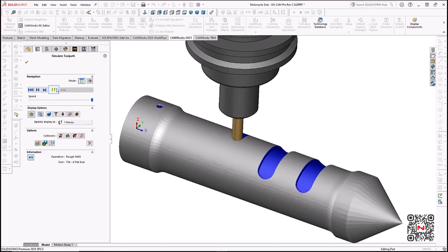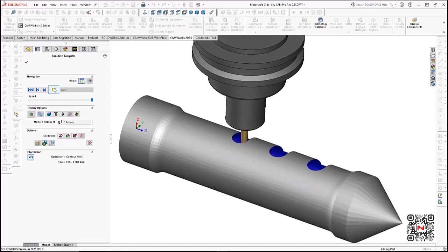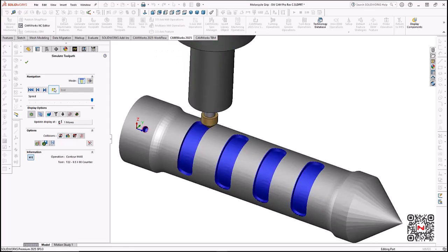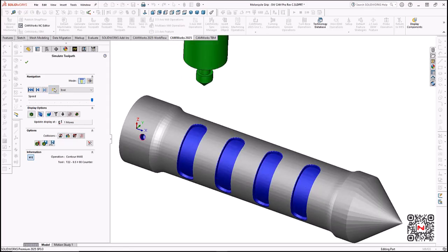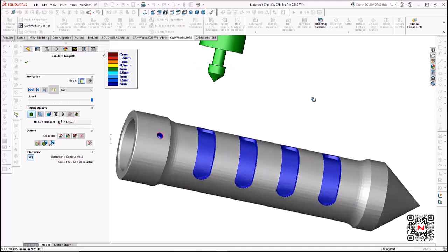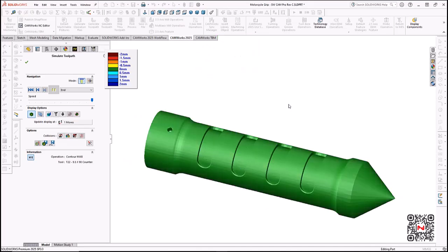And so very quickly the toolpaths have been updated thanks to the associativity that CAMWORKS has to the SOLIDWORKS model. And this is the associativity and the updating of the toolpaths. This is true about all 3 configurations. So if a change is made to any of the 3 configurations, then the toolpaths will update automatically. You can see here again, I'm comparing the machined model to the changed design model. And you can see everything is in green and looks terrific.